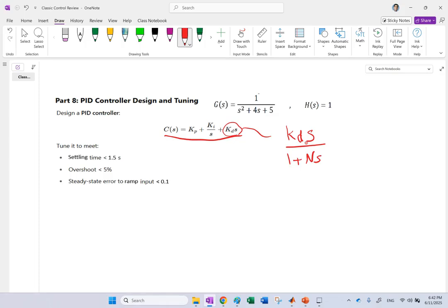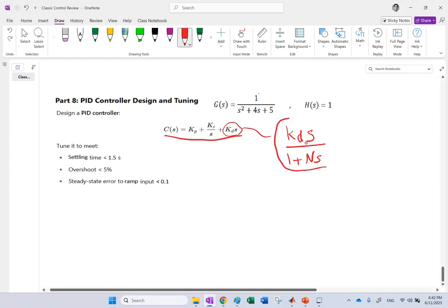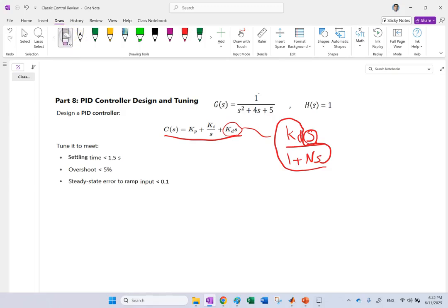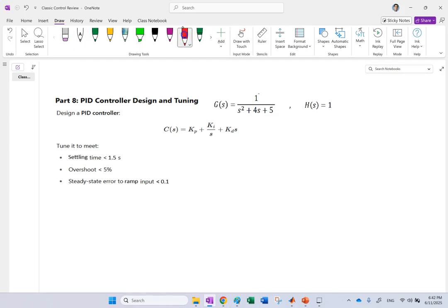And we can make it a high-pass filter as opposed to direct derivative. So this portion does a low-pass filter for me and removes the noise out of the signal. Then I do take a derivative, okay? So I can do that as well if my system has noisy signal. In this case, I assume it's just pure simulation. I don't have noise, so I just go with the original format of PID, not PIDF.